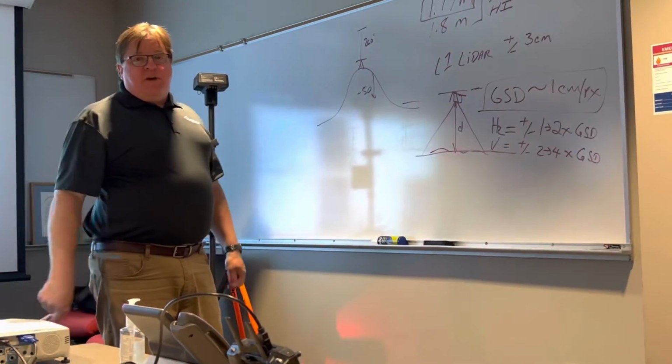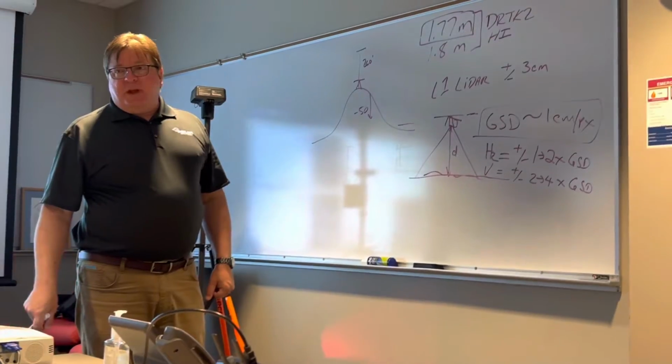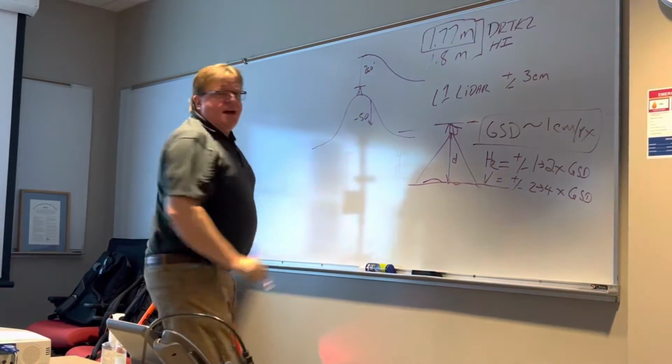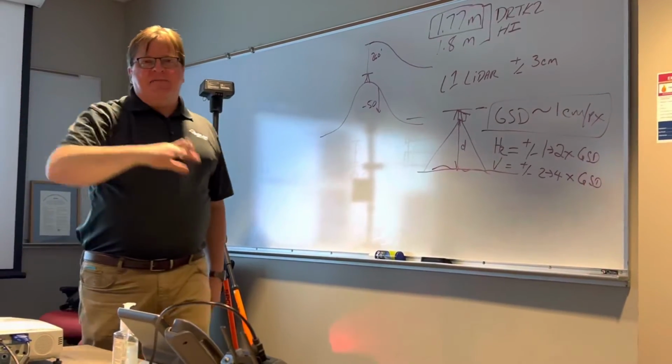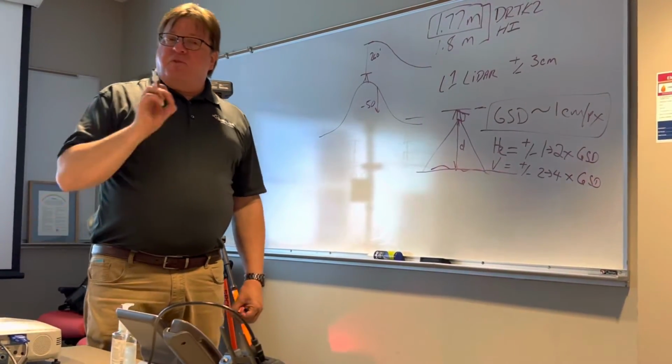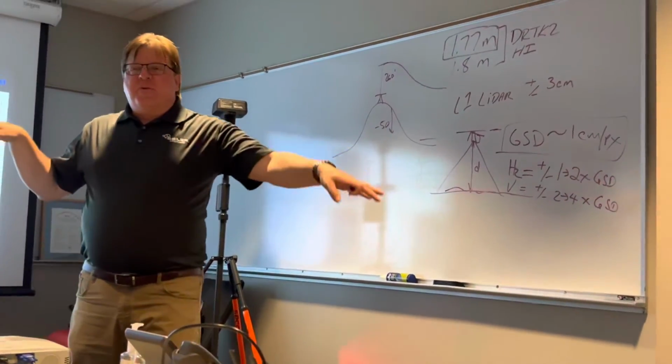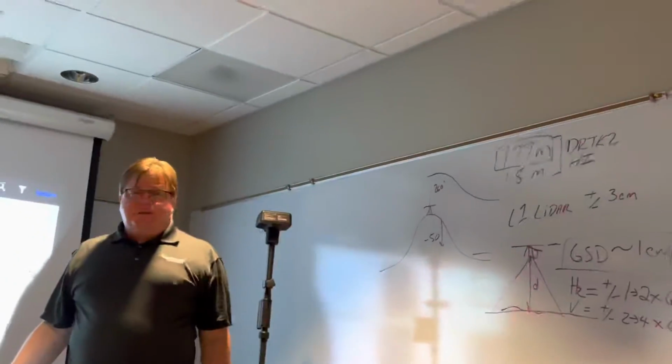There are terrain following capabilities with this drone. I can load in a model so that the drone actually flies in that kind of pattern to try to maintain that, if that's important to me, if I'm really shooting for high accuracy. If it slopes away down maybe 20 or 30 feet, I'm probably not going to worry. It's going to be good enough.